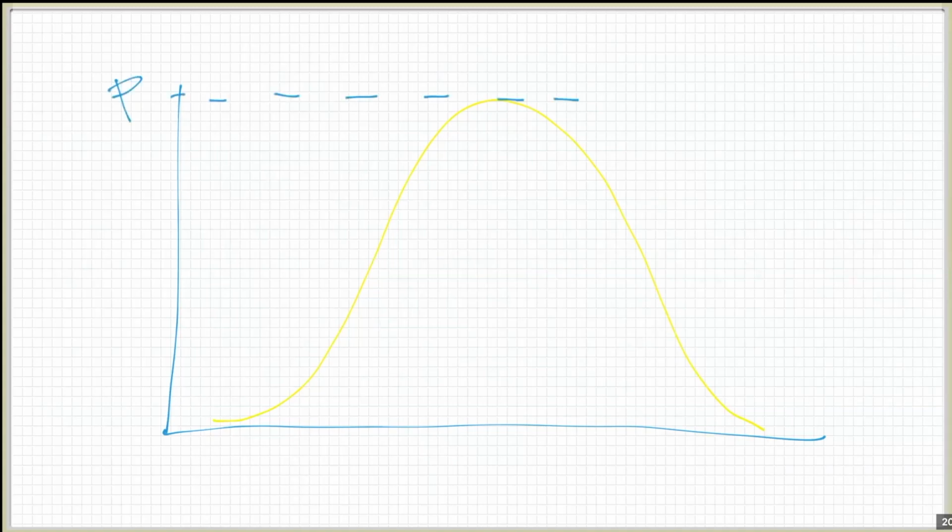That peak might be, let's say, 8 kilowatts of peak power. Now that might only occur on a really cold day, by the way, because of course panels lose power as they heat up. And we connect an inverter that can only put out 5 kilowatts. So our 5 kilowatt inverter, well, let's say not out, but its input can accept 5 kilowatts. And that's generally a current limit as opposed to a power limit, though both matter because power heats up the inverter.